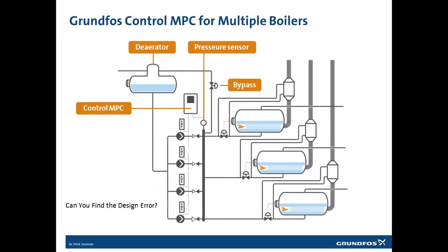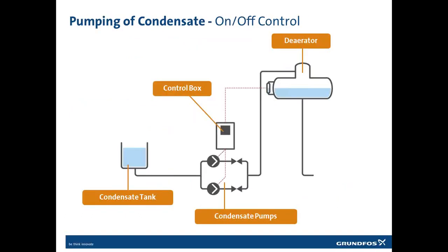When we are using on-off pumps, we will pump not cold water, but relatively cold water into the deaerator, and that will stop the process of degassing the water.